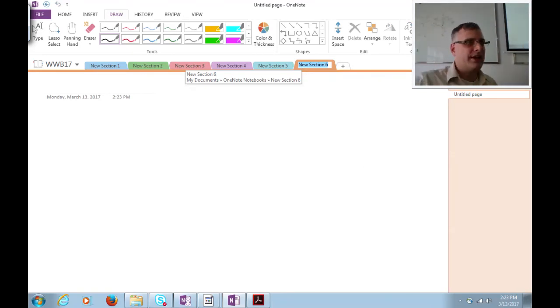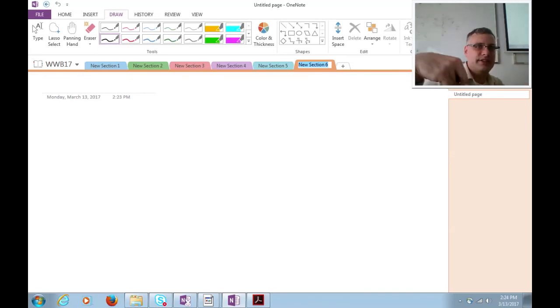Now, what we've been talking about so far has been balance coding for the purposes of trying to wring as much throughput out of the network as possible, out of your link as possible. We're minimizing the number of coded bits that you have to add to get it to behave like a balanced signal.